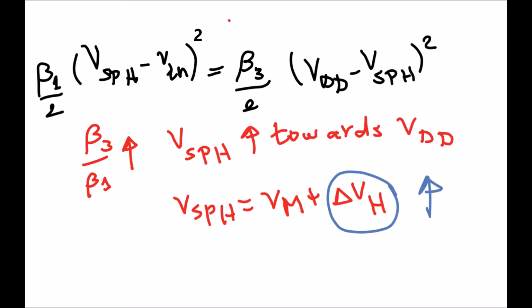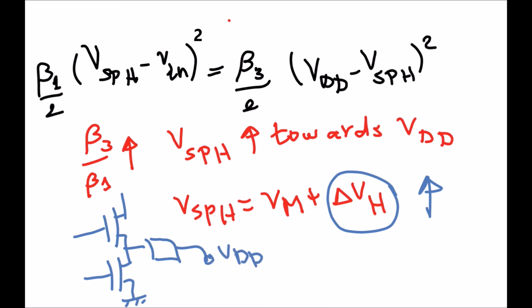We can look at it as if we have the switching transistor. If we increase the size of this transistor, it is some kind of a resistor. So if this resistor, N3, is low, the current passes through this feedback transistor, and this makes Vx increase slowly, which means N2 waits for a while until it switches on.